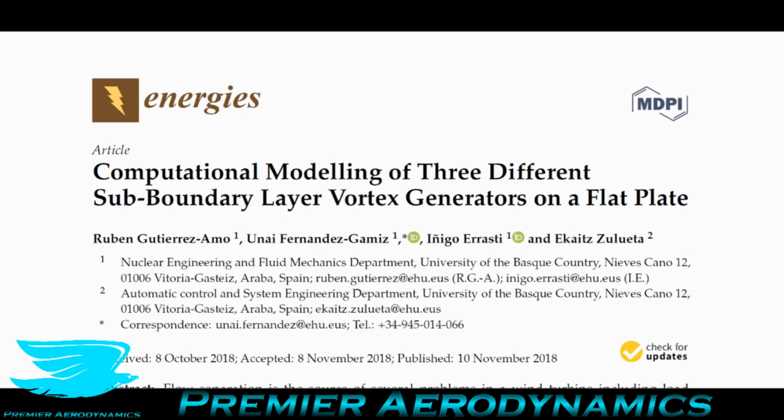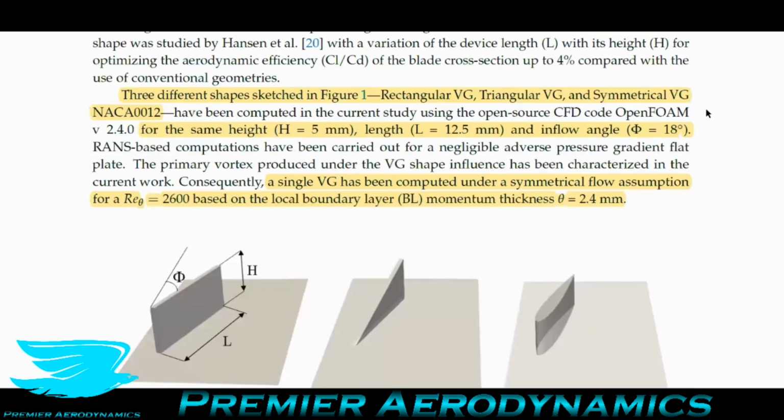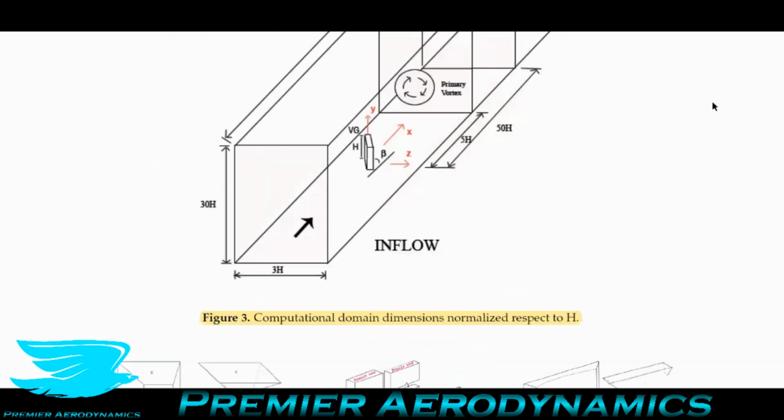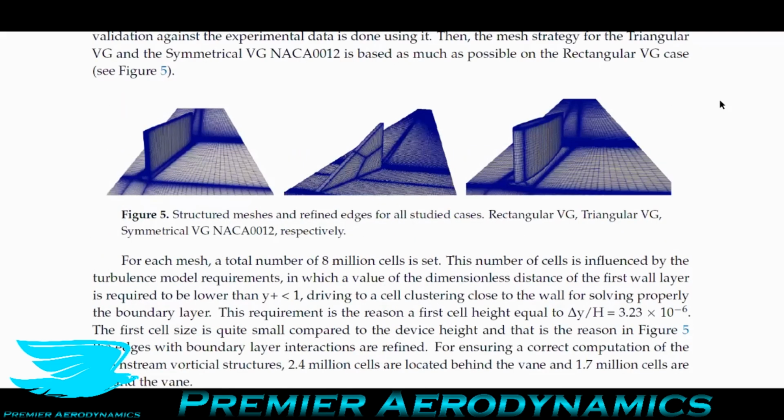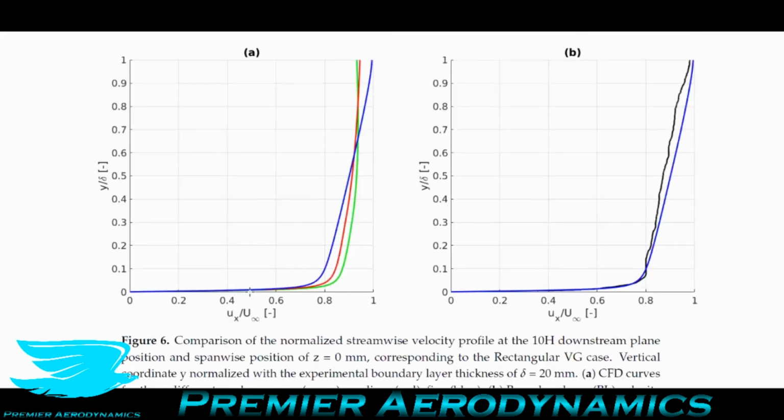So you've gone over the wing a little bit, and you have this constant pressure continually trying to decelerate the boundary layer. That's not a big problem for the upper boundary layer because when you get higher up in the boundary layer, the velocity is faster. So this velocity will reduce, but it won't start to reverse. But when you get closer to the boundary, sorry, the surface, the boundary layer becomes very slow. Now, if you haven't seen what a boundary layer profile looks like before, imagine an exponential curve, where it starts off fairly slow and then really ramps up and goes higher. So that's what a boundary layer profile looks like.